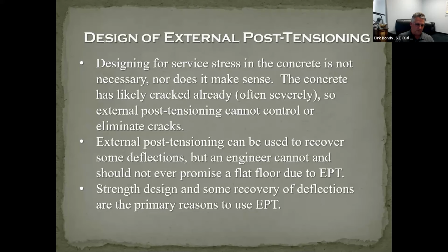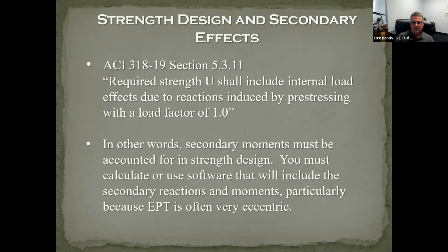Never promise that external post-tensioning will do magical things, but it won't create a flat floor. You're really talking about strength design, and you're going to get back some deflections. And that's what we're doing with external post-tensioning.